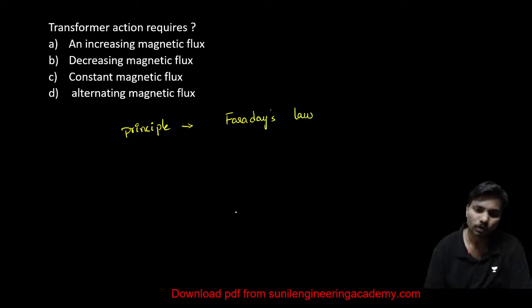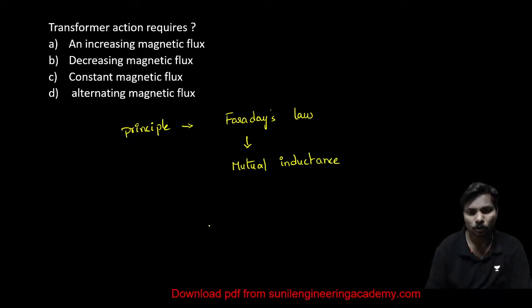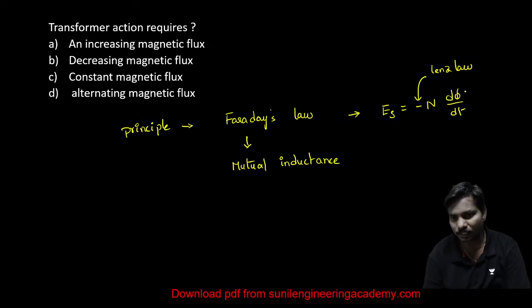Faraday's laws. In this particularly, you can say mutual induction principle, or mutual inductance. According to Faraday's law, an EMF will be generated. Here there are no rotating parts. Here a statically induced EMF is developed, minus N d phi by dt. The minus is Lenz's law. Whenever the flux is changing with respect to time, whenever there is a time varying flux,